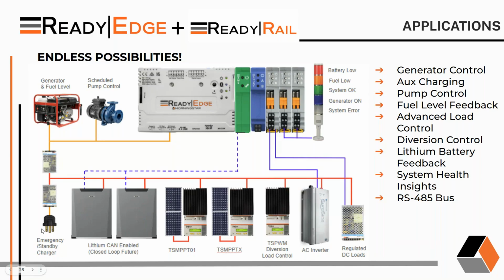A common application for security customers. They show up to a system because there's a problem because you're running a security trailer. First thing you do is plug in your AC, like kind of like shore power, but it's on the truck, into the cabinet. Get that battery charging up, make sure everything's turned back on, and then you can start troubleshooting. We have 2 lithium batteries in this case, all tied together to the BMS so that we can see the SoC from the whole bank of batteries together.